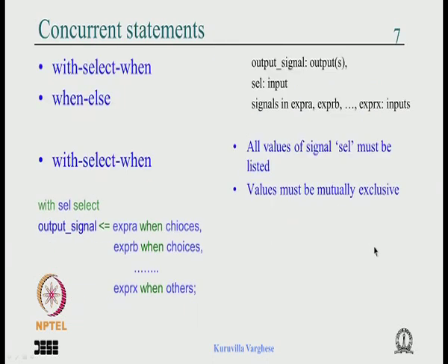And then we have looked at the important part, the concurrent statement. As the name suggests, this is used in the concurrent body, that is in the architecture statement region. This cannot be used within a function or a procedure or a process, it has to be straight away used in the concurrent body or the architecture statement region.